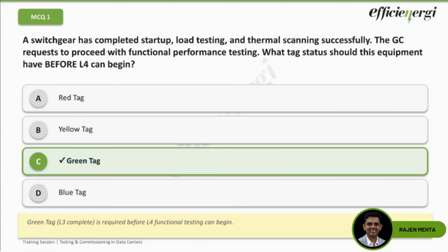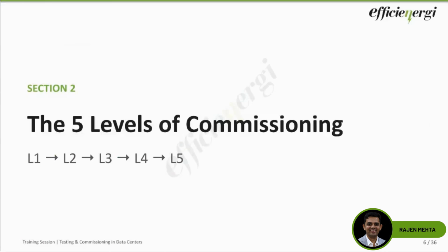Yes, definitely the answer is green tag, and it is required to be completed before the L4 functional testing can begin. Okay. So let's dive into now the 5 levels of commissioning.